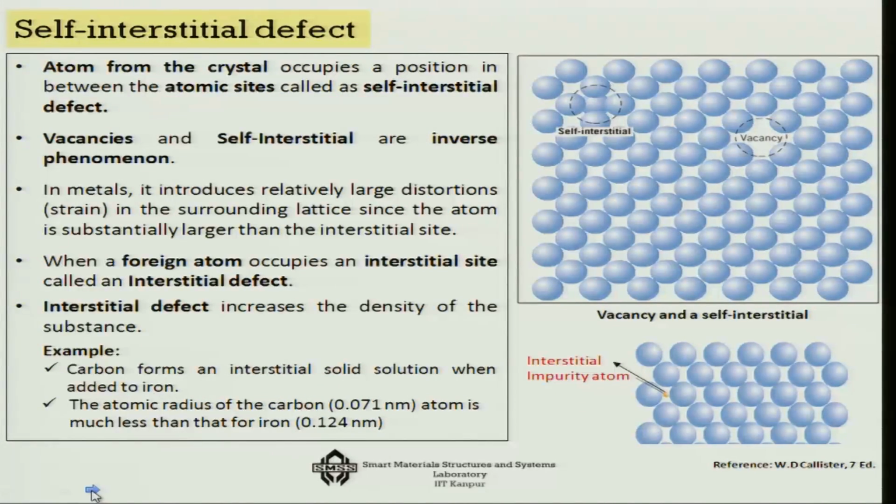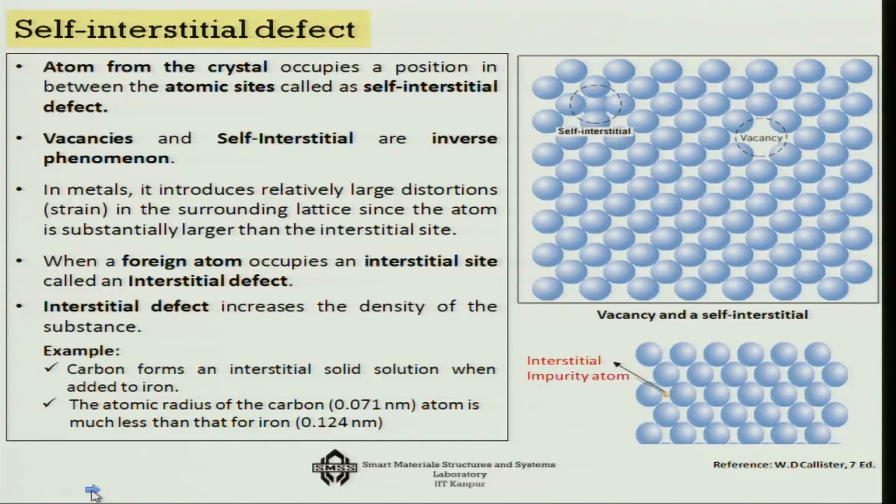Now, there is another form that can happen when the vacancy is there. Because you will never see a very pure material, suddenly an impurity goes and says, okay, there is a vacancy, let me push myself inside it. That is called interstitial defect. If an atom from the same group pushes itself in, then it is a self interstitial defect. Sometimes atoms of different kinds, like a foreign atom, can occupy it, then it is not self interstitial, but just an interstitial defect.